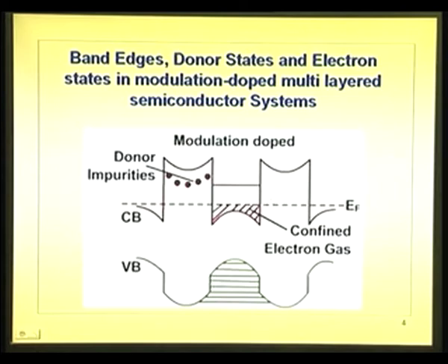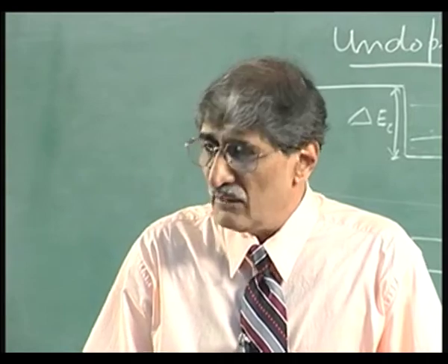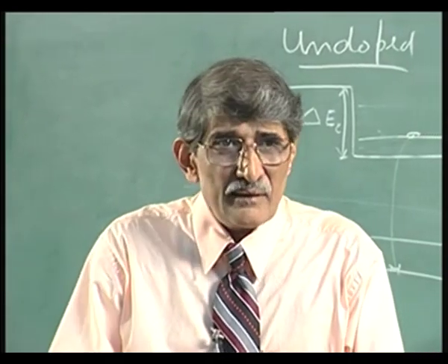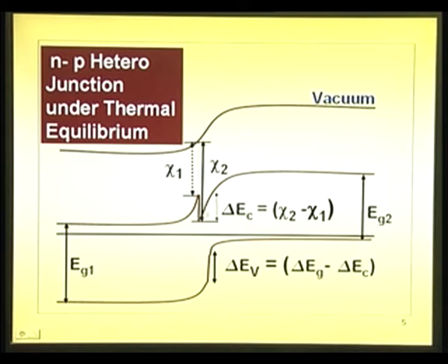Now, how thick that layer you want is decided by where you want the energy levels for a multi-layer structure. But in this particular case, where you have only 2 layers, all that you are looking for is this notch, which is created by this. In fact, we have shown last time how to generate this energy band diagram for aluminum gallium arsenide layer. When you have multi-layer structure, just let me go back once. Same thing holds good. You can see there is a notch here from this side. From this side also there is a notch. So, the confinement takes over the entire layer, whereas here the confinement is here only, because this is a thick layer compared to this.